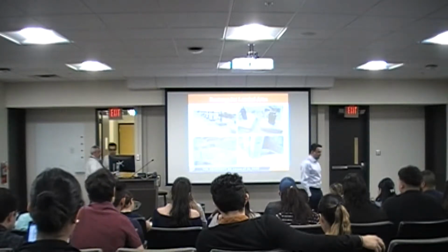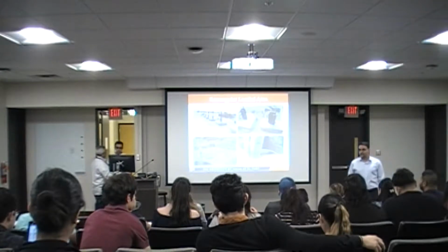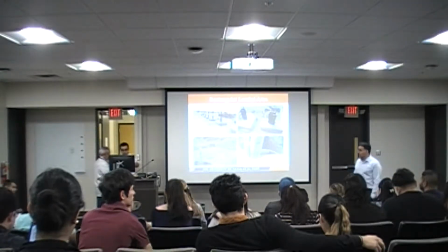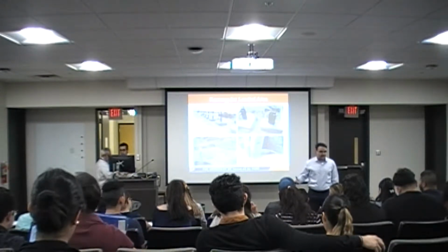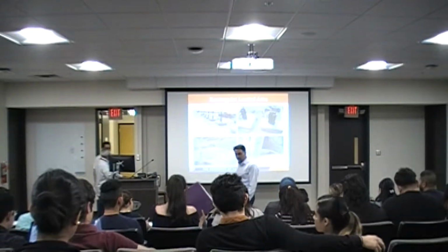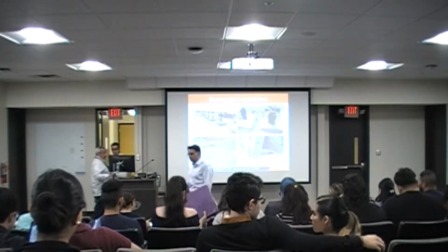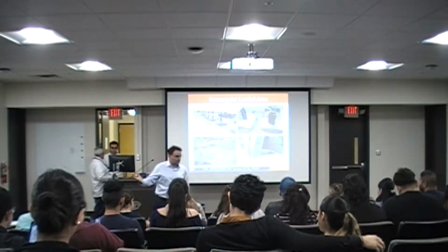And also we talked about the factor of safety is closely tied to the importance of the structure, right? So the importance of the structure, remember we talked about the earth dams. Typically the factor of safety that we use for the earth dam, because of the fact that the consequence of failure and the fatalities are going to be significant, they use a factor of safety of 9, for instance.